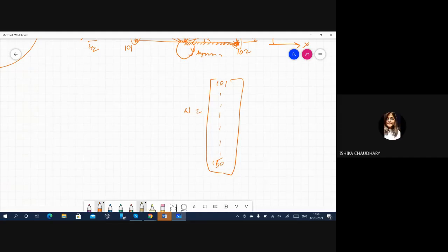I'm asking, does the data have any value of yield strength already in it? Yes, sir. It has 0.2% yield stress value and 0.02% yield stress value. And what have I asked? Have I asked to calculate yield strength for all the cycles? 10 cycles, sir. So for 10 cycles, you calculate 2 yield stresses for each cycle. So per cycle 2 values.